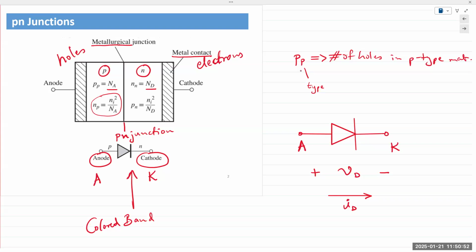This one. So in a P-type material, if you are infusing it with acceptor atoms, you have an excess of holes. And then you have the electrons, but you have not infused with any external impurities. So the only electrons present in the P-type material, assuming there's no other impurity in there, are the intrinsically generated electrons. So I believe your question is an explanation for this equation on both sides, right?